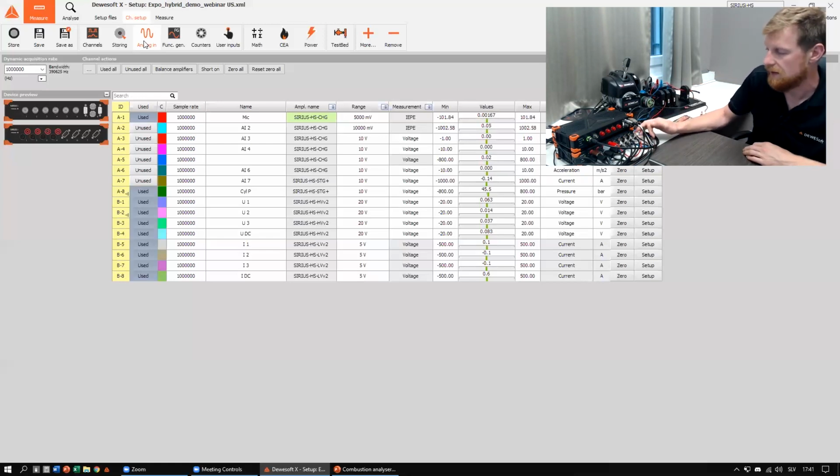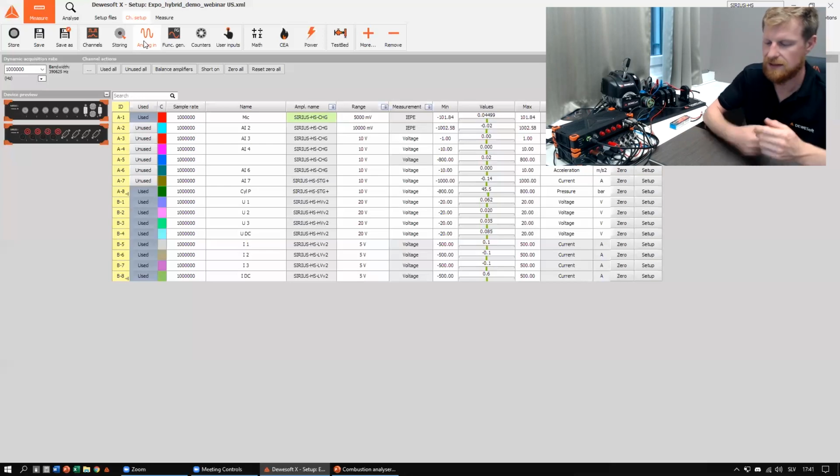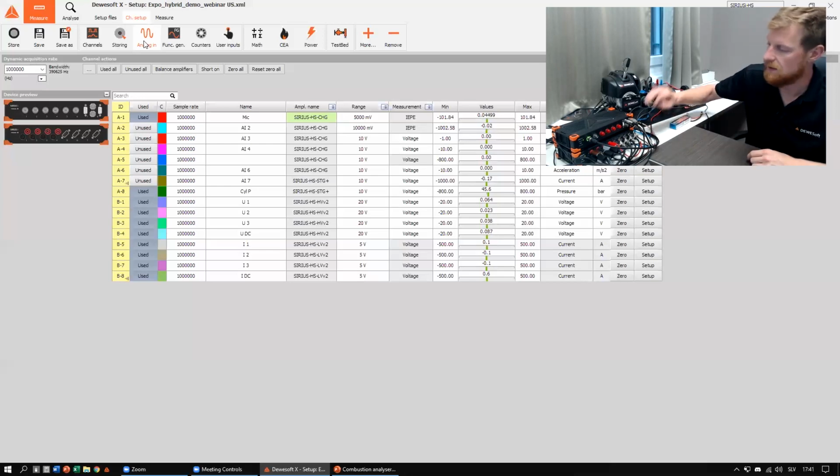And the nice thing here is that they also have test chips in connectors, that is basically like an electronic chip that has the sensor database inside. So as soon as this is connected to a series instrument, the sensor is read and everything is set automatically. So all the scaling is set automatically, and the sensor type or amplifier type is set automatically via this.